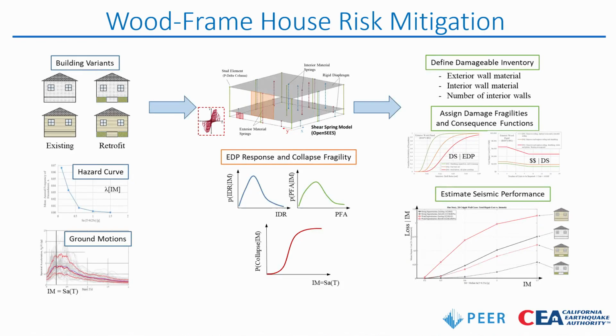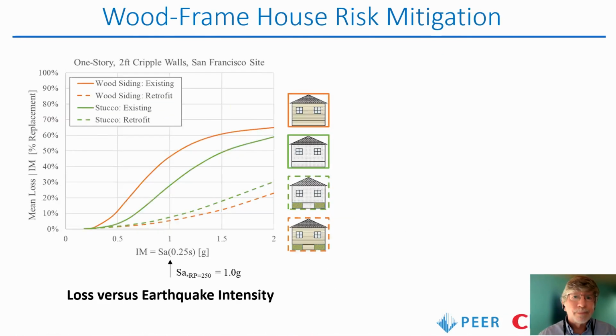So I won't go through all the details, but briefly, we could apply the performance-based methodology, similar to what was applied to the tall building, but in this case, it's to look at a bunch of different archetypes, kind of prototypes of different configurations of houses, 1-story, 2-story, made of different materials, building computer models of them. And the point of this study was to try to demonstrate what's going to be the benefit of taking the effort and spending the money to do this retrofit of the foundation.